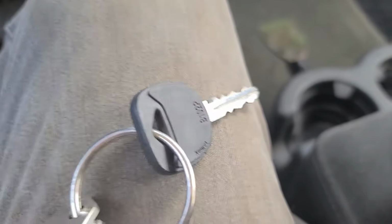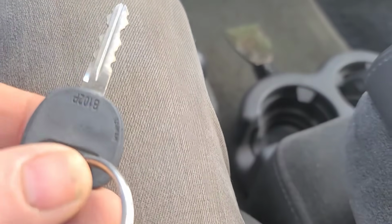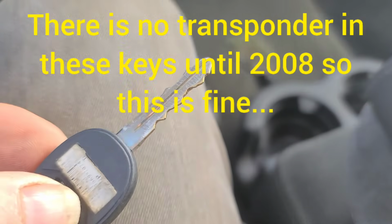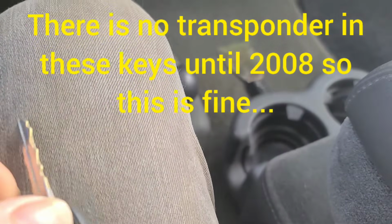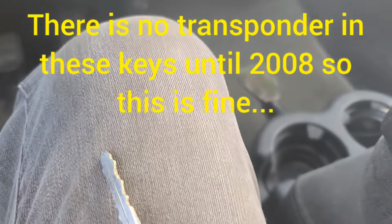Well, the first thing I noticed before we even go to crank this thing is that this is not an OEM key. And I'm not sure if this has got security in this key. So that could be the cause of the problem.